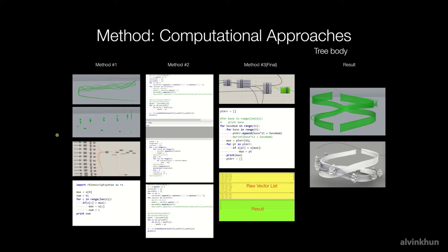This is inefficient and hard to manage graphically. The second method is to feed the entire branch list into the GH tool. Inside GH we have developed a list parser to convert the Grasshopper row list data into a manageable 2D array. This method is comparatively more efficient than the first one, but it is not adaptive to parametric input, since we have to manually adjust the input of the parser method.